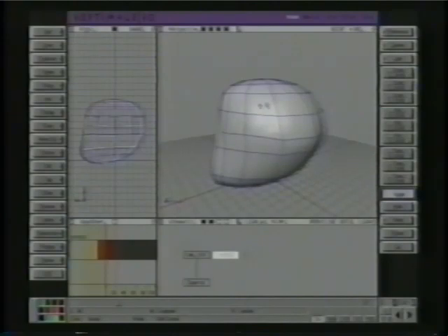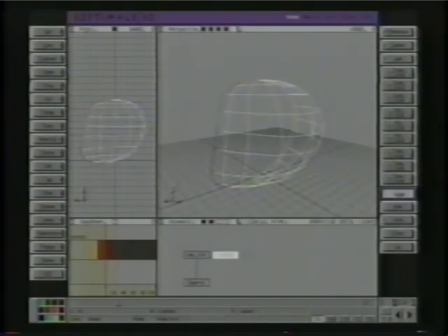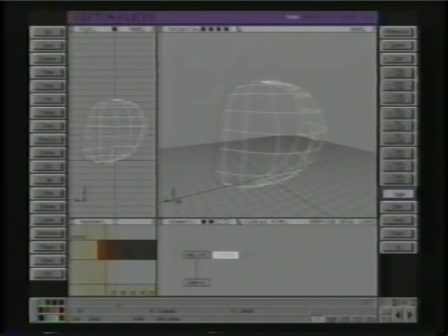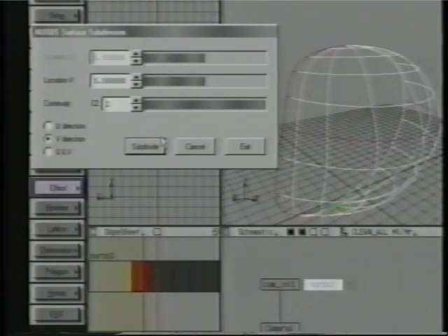Now you can start putting in the mouth and the eyes. So I need to switch to wireframe mode for that. I can turn off lines to make it a little bit easier. Like I said earlier, using effect subdivision on a NURBS surface or curve doesn't change the overall shape, which is very beneficial. If this were B-spline and you use add point, it would change the overall shape when you add localized detail. Go ahead and use effect subdivision. Now we can add that localized data.